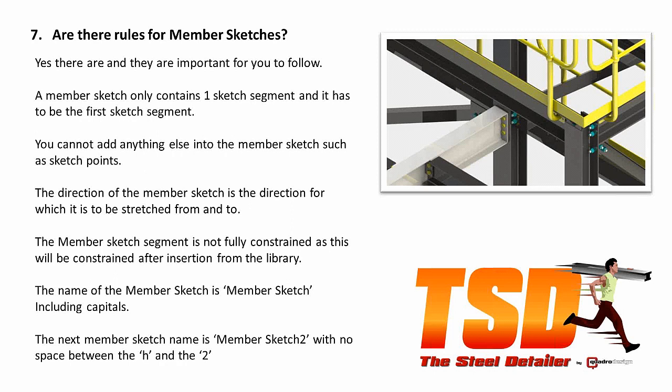And now, all of our members, all of our braces, all of our trusses, stairs are a little bit different because we've got two member sketches to drive that, but most of our trusses that may even be diagonal, we draw horizontally in the member sketch, in the member weldment under the member sketch. The reason for that is because when you go and put that on a drawing, essentially you don't want it rotating up on you. You want to have it so that it's horizontal and the ends do the rotation.